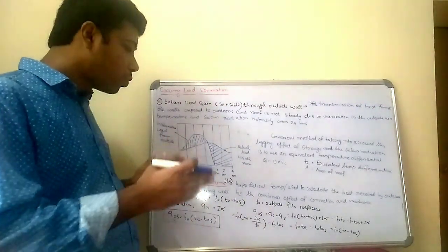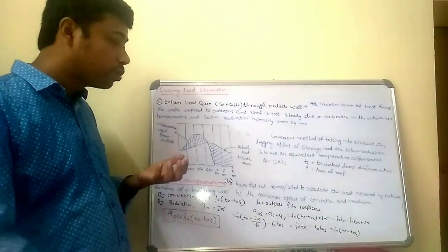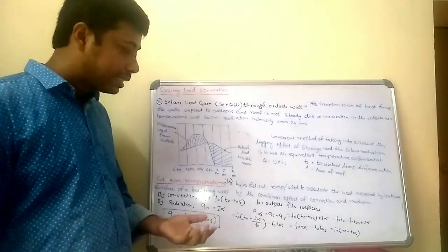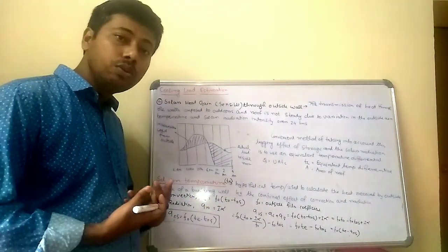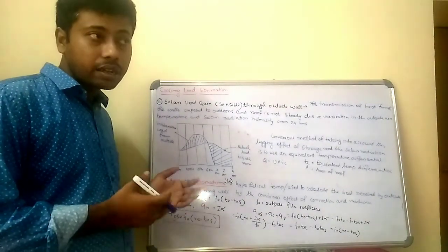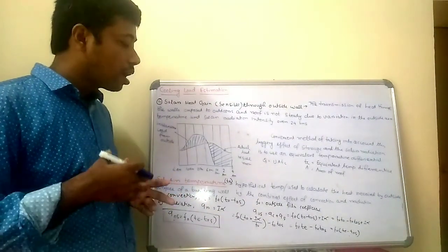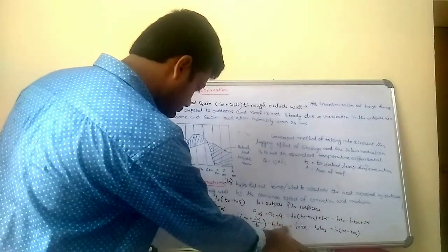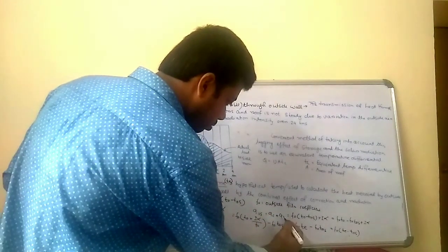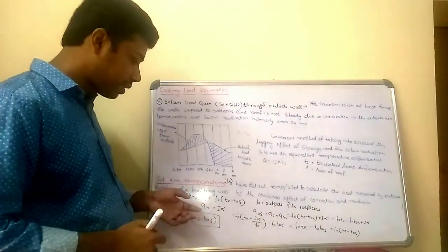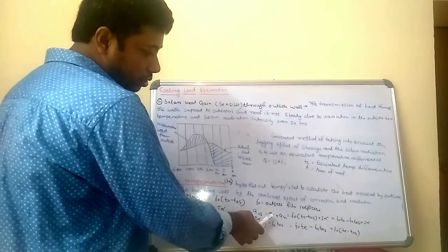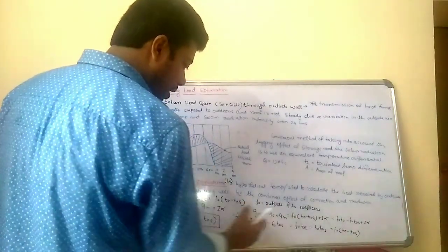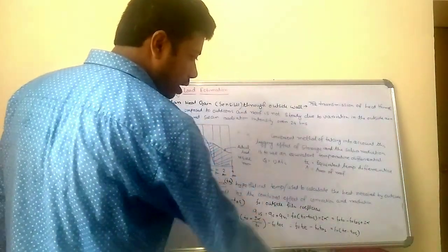So when you calculate the sol-air temperature, to calculate the cooling load estimation, that will be your QAS, the summation of QC plus QR. That is the heat received by the convection method plus the heat received by the radiation method. So QAS is QC plus QR. Now in terms of QC, you can put H0 into this term, and similarly QR is equal to I into alpha.